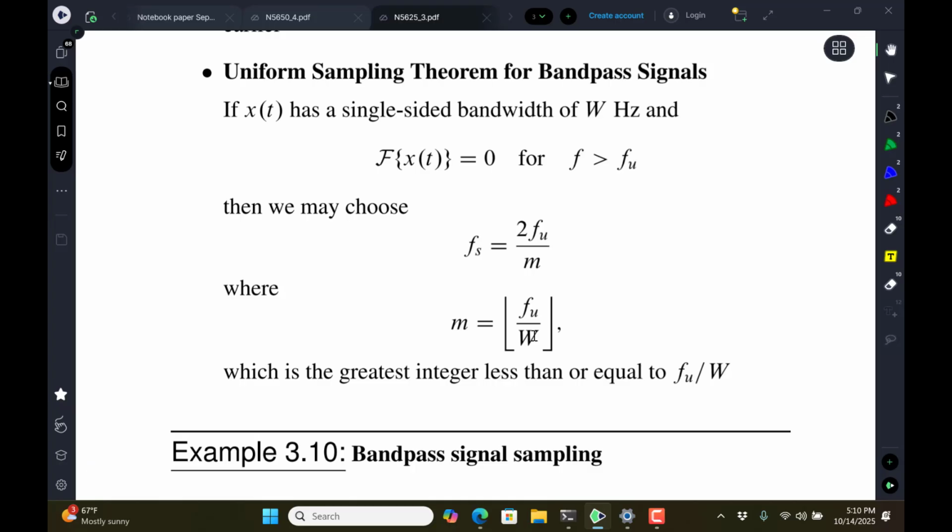See if it works, okay? It's not a big deal in this class, but it is something that shows up in software-defined radio, and if you end up working in a company where they have IF sampling or undersampling like this, you'll look at it, and I don't want you to go away from this class saying it's always got to be greater than twice the highest frequency, and if you're not doing that, it can't work. I want you to just accept the fact that yes, it can work, and it's done frequently.